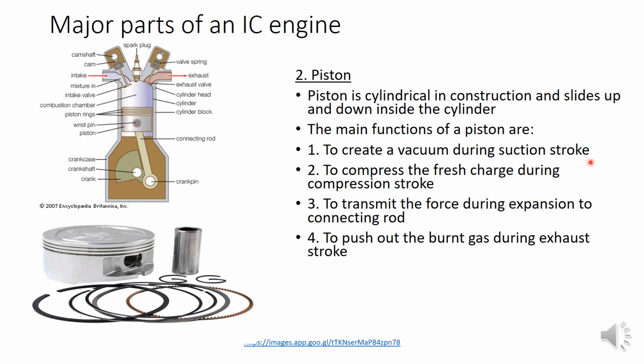This we will study in detail in the next session. So in all the 4 strokes the piston has some function. In the suction stroke it helps to create vacuum. In the compression stroke it helps to compress the charge. In the power stroke it helps to transmit the power to the connecting rod. And finally in the exhaust stroke it helps to push the burned gas out of the cylinder. So all these are the functions of